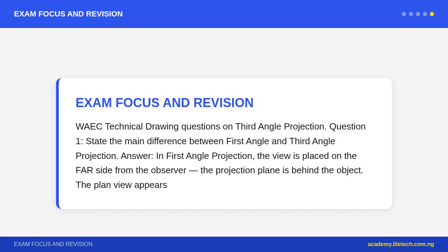If the system is not stated, a manufacturer in a third angle country reading a first angle drawing would confuse left and right, top and bottom views, potentially building the component incorrectly or mirror reversed. The projection symbol eliminates all ambiguity.